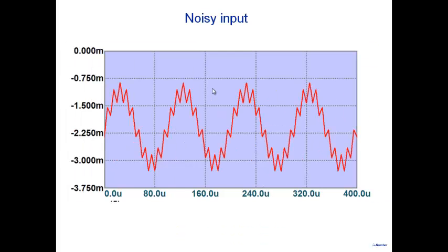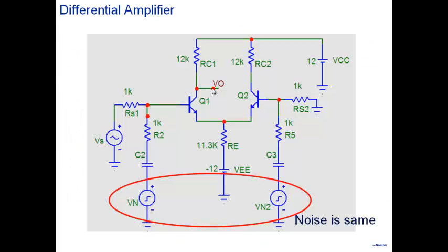So there are many situations where you have a wire coming into your system and noise is getting coupled into it. One signal is coming in from some place and noise is getting added to it. What you can do is run another parallel input along with your real input. Noise will get coupled into that as well. Then you apply one to one side and the other to the other side, and the two just cancel each other.